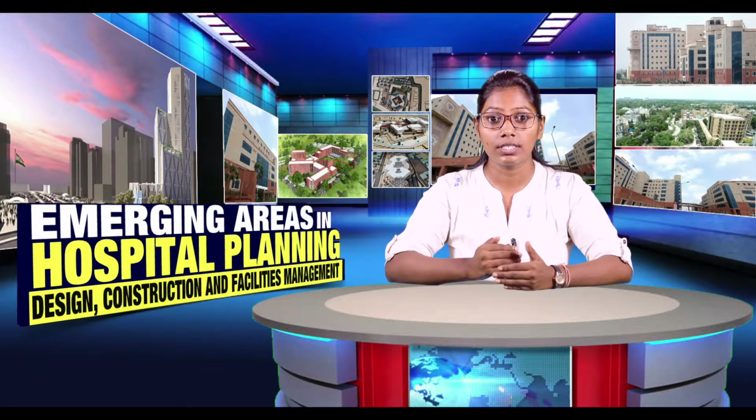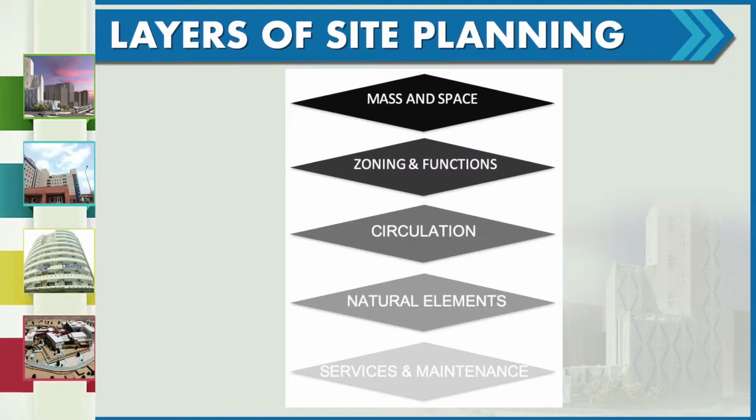What are the various layers of site planning? First and most is the mass and space, which includes building and other open spaces around. The second one is zoning and functions, which includes the program and various activities. The third one is circulation, which includes the vehicular movement and pedestrian movement. The fourth one is the natural elements, which includes the water body, trees and other earth forms. And the last one is services and maintenance such as STP, electrical services, etc.